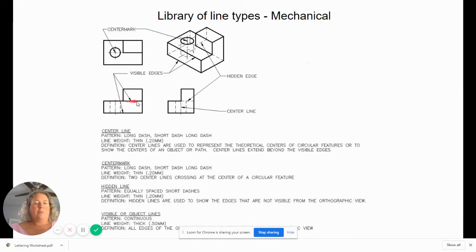In this view, we have hidden lines just where the circle would pass through the solid here. So those are hidden lines to show that circle's diameter there. And then in this view here, we actually have hidden lines here, where this would become a hidden line if we're looking from this direction. This view is looking in this direction. And we also can see the hidden lines beyond of the hole again. The distance between the hidden lines would match the diameter.